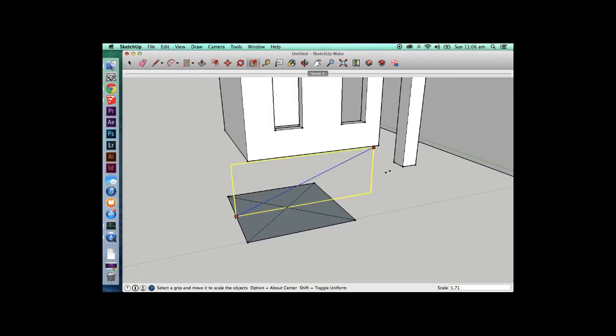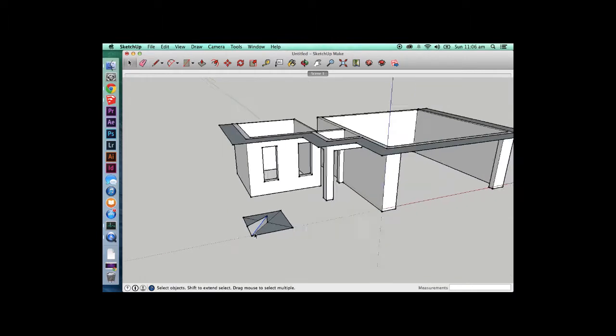Scale this line up, so just press S to scale, click this top corner, scale it up. Now you don't want to scale like this, because that will change the angle. So you want to change just the two opposite corners. Scale it through this center point, draw a line, intersect them, and draw a line from that to this corner, and there's your angle.